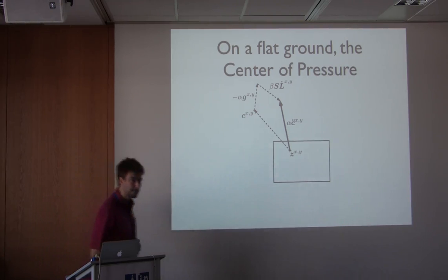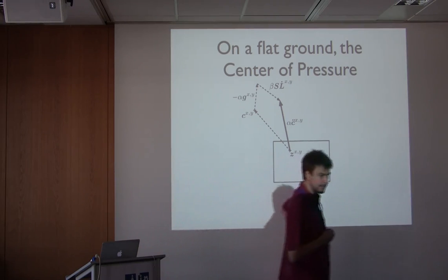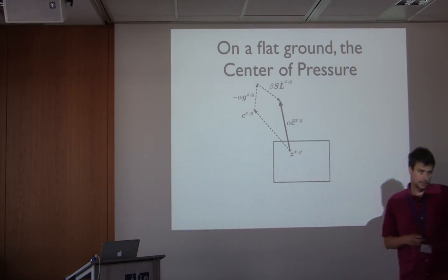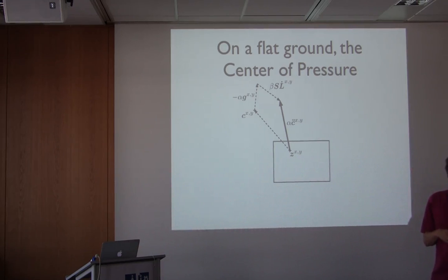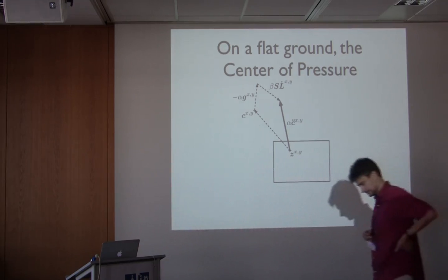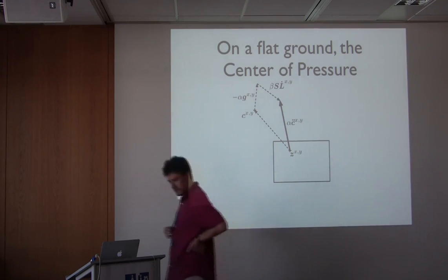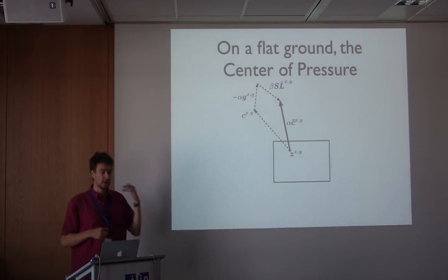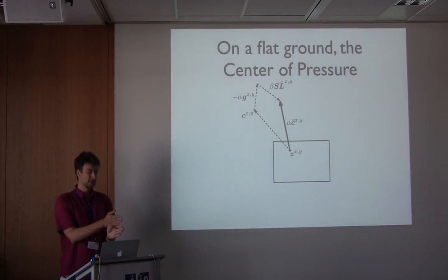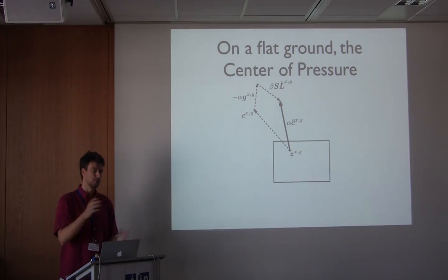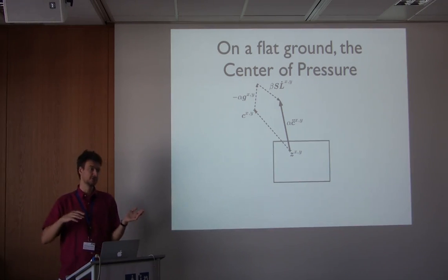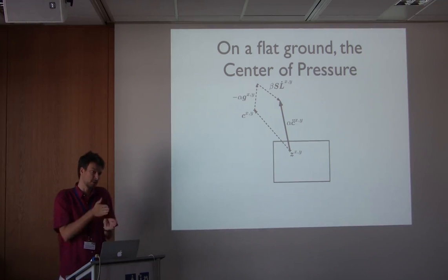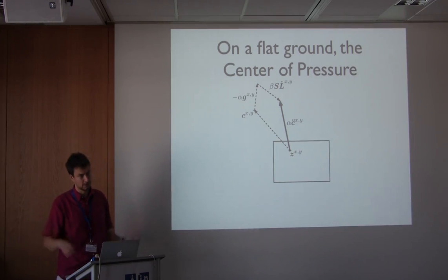With our skating robot, that turned into quite a challenge, because skates are interesting in that respect: the ground reaction force is very strong sideways and basically zero forward. Yes, but usually in this case you consider the limit, which is to have absolute friction in one direction and absolutely no friction in the other direction. So once again you just get rid of this friction coefficient by considering a non-slipping constraint, so that you can go freely in one direction and absolutely not in the other direction. That's usually what's done.